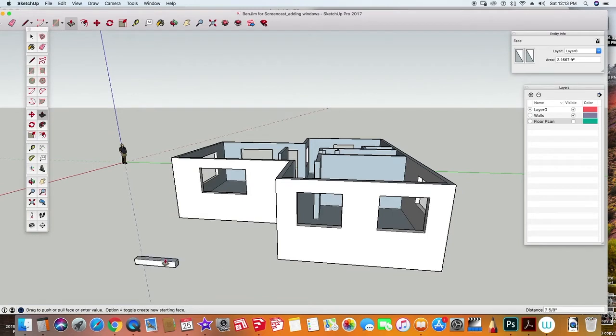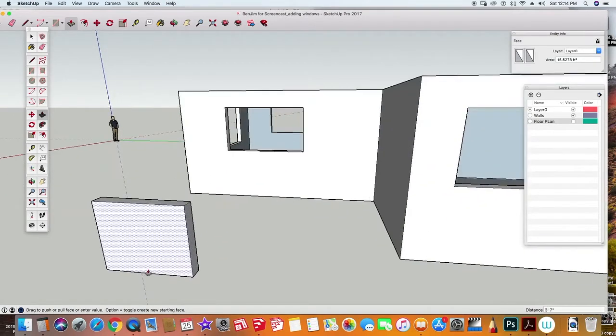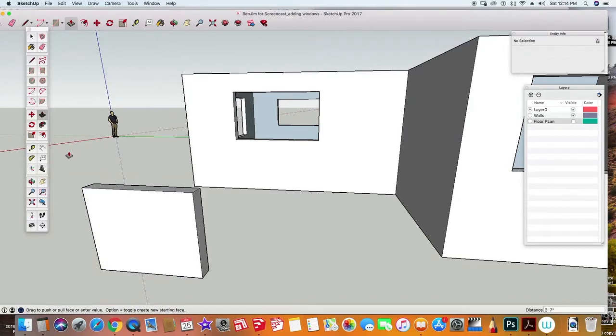Now I'm going to pull that shape up, or extrude it up, to the height, which is 3 foot 7 inches. And here's the outer part of our casement. All right, now we said that what we wanted to do is make 2 rectangles inside of each other, and on top of that there are 2 panels inside that rectangle. So I'm going to first put in where the half mark would be in the window. We know that the window is 4 foot 4 inches, so I'm just going to pull a guideline here in the front that is 2 feet 2 inches, and that gives me the middle of this rectangle.